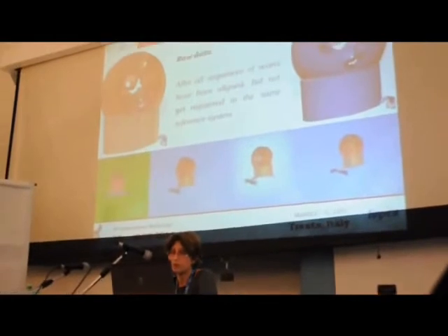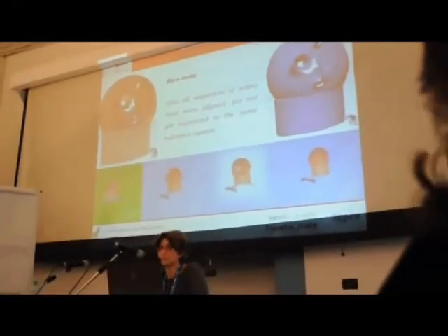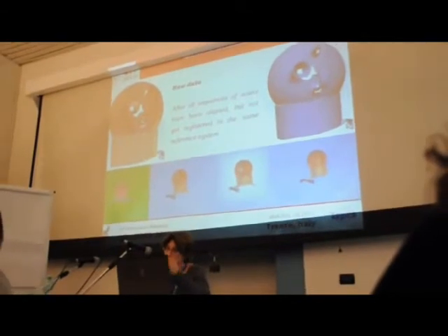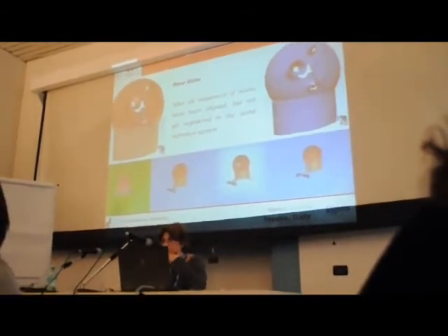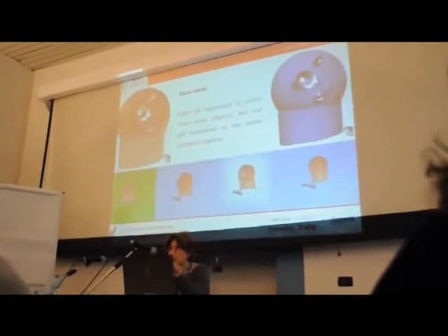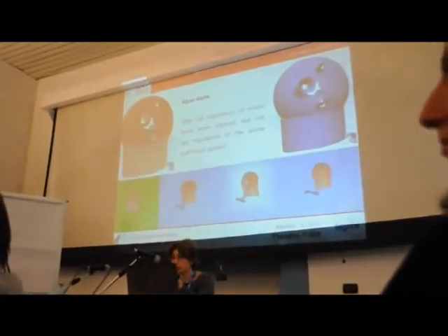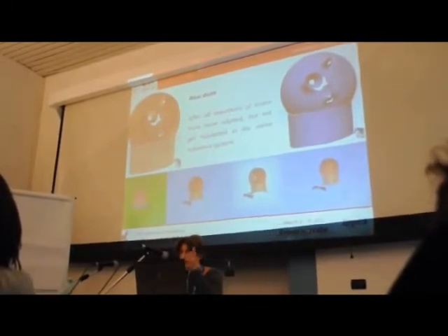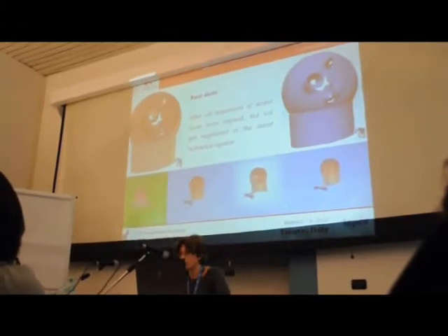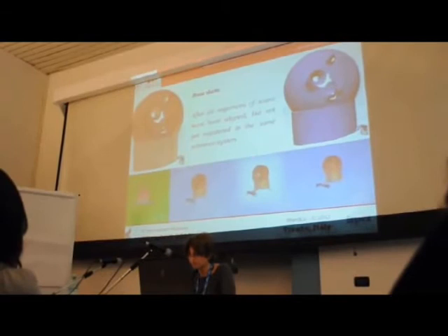Okay, here I show you how raw data appears in Scan Studio, the Next Engine software. For each position, we performed sequences of scans, they're called families, completing a 360 degrees rotation on the vertical axis to capture the body of the object, and triplets for the summit and the bottom of the object. Sometimes also single scans are needed for integrations.